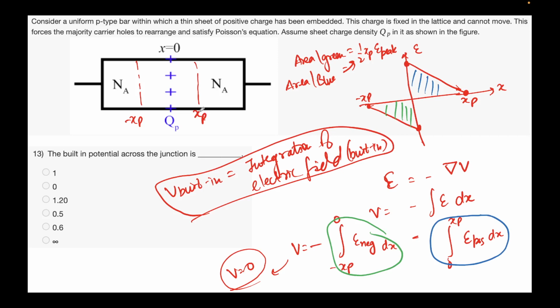So if we inject some carriers, let's say electrons or holes, it will play a role. For equilibrium, it does not seem to be playing a role, but that's how you approach these problems. So this was the problem. It just condensed everything that you have learned. We solved all the problems which were based on the formula, but in this problem we went back to where we started, that is, solving the Poisson's equation and applying the depletion approximation.